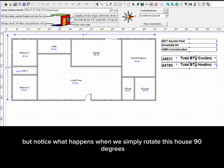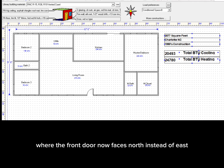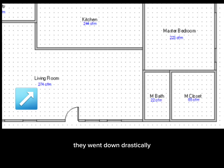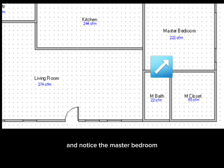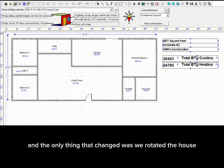But notice what happens when we simply rotate this house 90 degrees, where the front door now faces north instead of east. Notice what happened to the CFMs required for our living room. They went down drastically, 274 CFM as opposed to around 100 CFM more when we had the house at the other rotation. And notice the master bedroom. It now needs way more CFMs. We were at 184 before, now we're at 223. We might even have to put 3 supplies in this master bedroom. And the only thing that changed was we rotated the house.